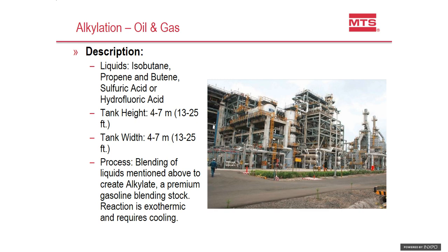Alkylation, so this is part of your downstream, your refinery. It's a step within the blending process to help boost the blend rating. Here within an alkylation tank, you're actually looking at 3 liquids in the tank. So both of your measurements are an interface measurement. So you need to be very concerned about whether or not the technology is going to be good at measuring interface.